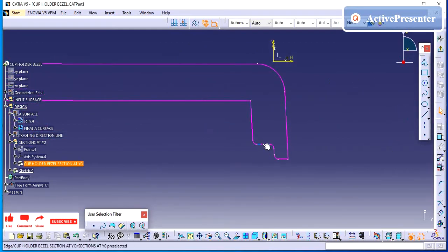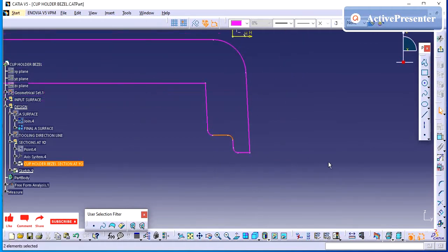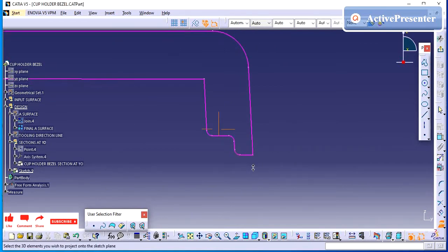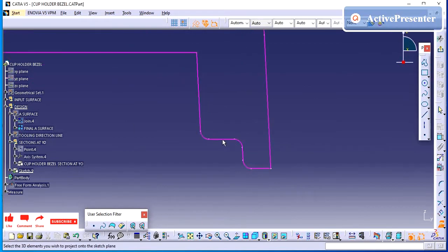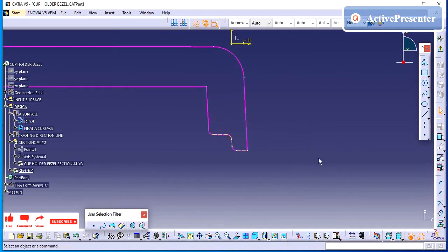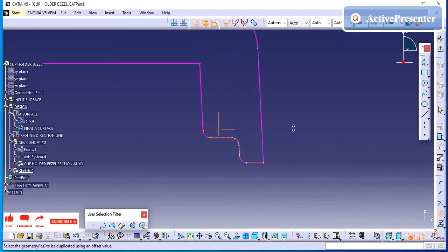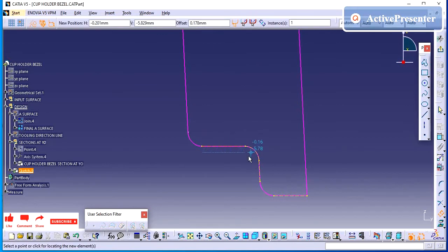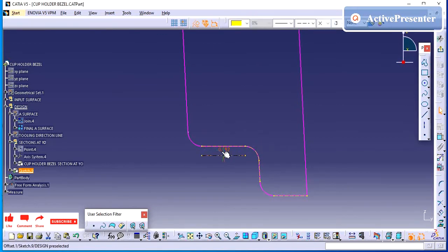So my part is going to have the attachment in this area, the environment part. So I am going to maintain the 0.1 mm clearance between these two parts. If you see, it is assembling from the top so that it will have the full contacts if I have maintained the 0.1 also.